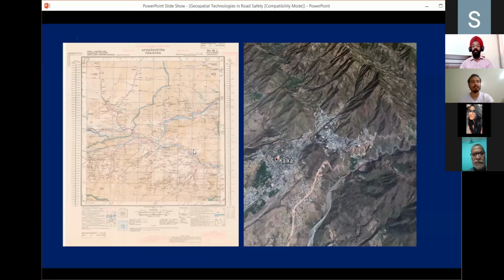Drastic visualization change. If I am planning something in this particular area, like construction of a road or a thermal plant, I must be aware of what type of area it is, whether it is a hilly area, or a plain area, or a valley. So I have to take care of the terrain information of that particular area. In the Survey of India topo sheet, we generally have to deal with contours. As engineers, we know what contours are. Contours are imaginary lines joining points of equal elevation.